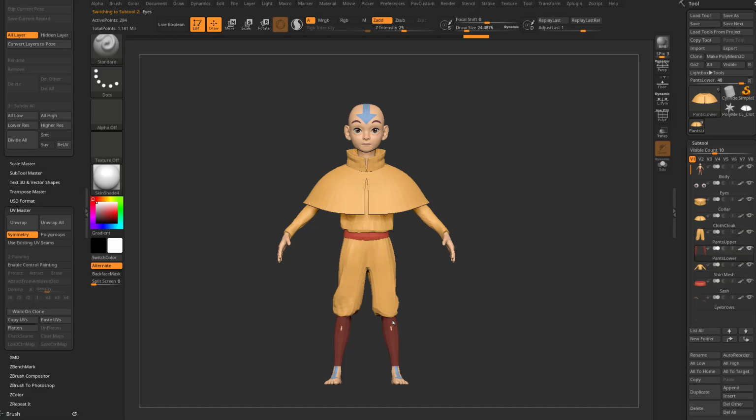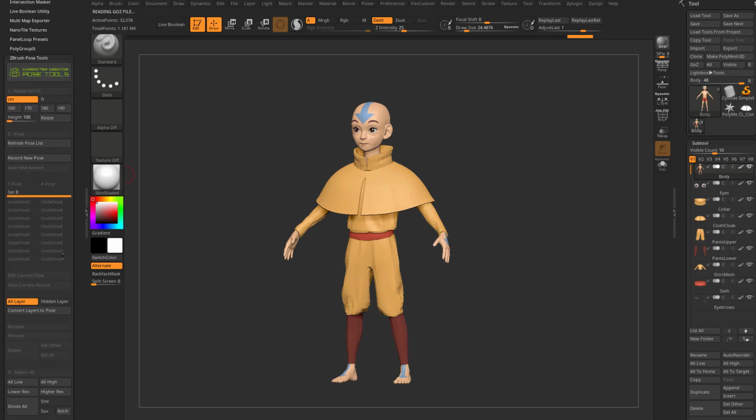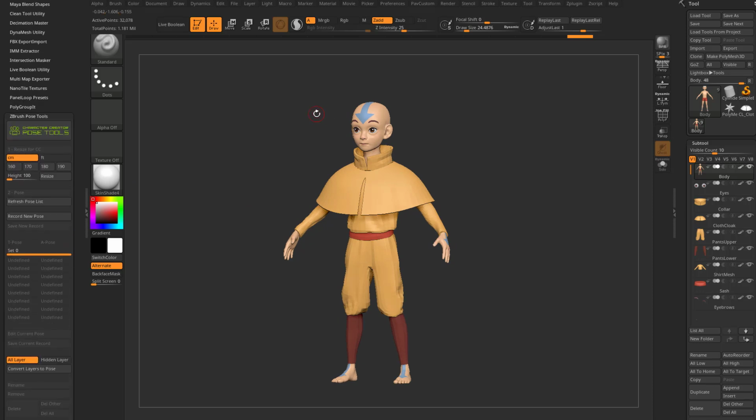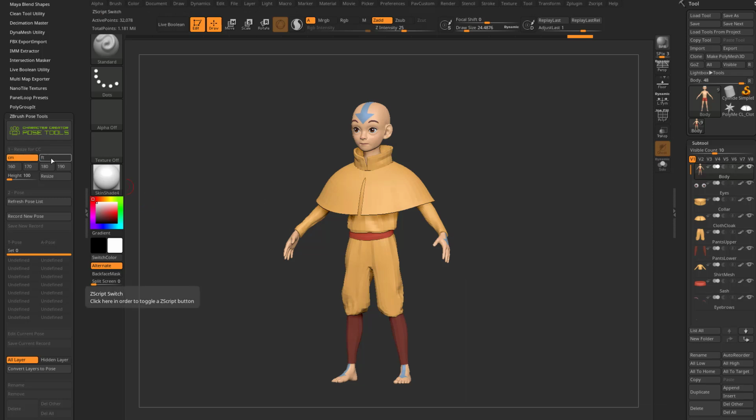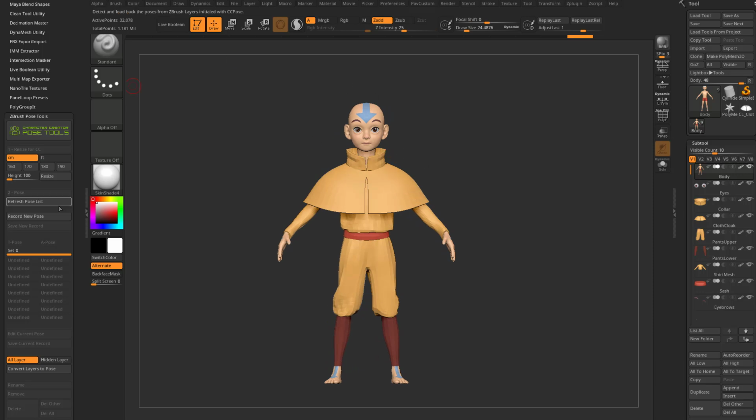and this will make sure, again, that all of our objects are in the exact same position from Character Create to ZBrush. You're going to see it nudged him slightly. Another thing I should mention, before we sent this over, and again, if you watched the last video, you're in good shape, we did resize this character. We had our body selected, and then of course we can choose centimeters or feet, choose one of these presets, or dial in the slider, it's up to you, and then hit that resize button. So he is sized appropriately in Character Creator. So we've nudged these verts into position that match Character Creator.